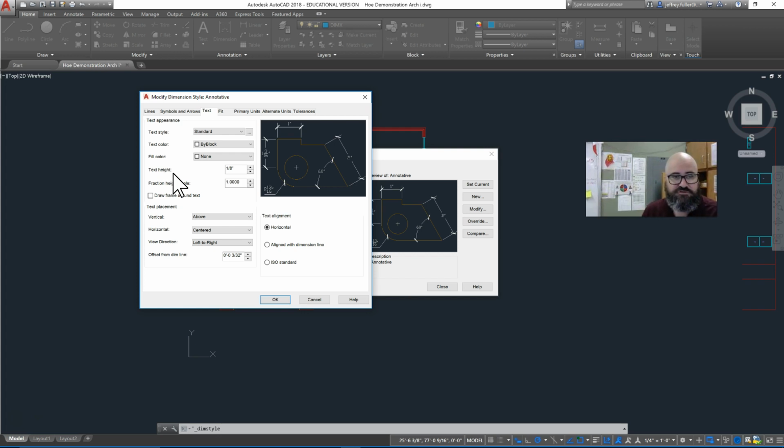Depending on other settings that you may have changed in your computer, which I've seen done, and I do not know why it does this, I can set mine for 1/8 on this computer and go over to someone else's and set theirs the same way, and the text size comes out different. But you may have to play with that just a little bit depending on whatever other settings may have been changed in the past during your design, I think, anyway. But right now I have it for 1/8, so go ahead and try that first.